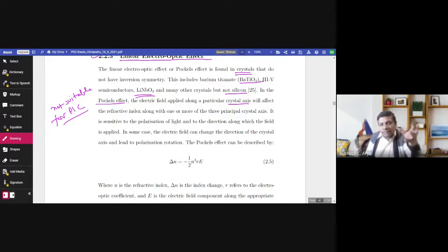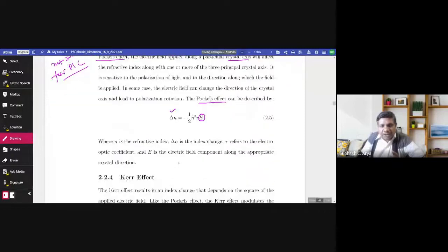So till now, whatever development could take place, it was because of this lithium niobate, which is an excellent optical material. Its refractive index changes with very small voltage also. This is popularly known as the Pockels effect. Most of the time, wherever you have seen a lithium niobate based optical modulator, it works on the Pockels effect.